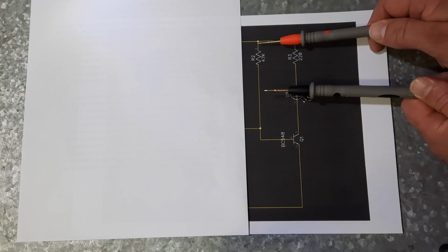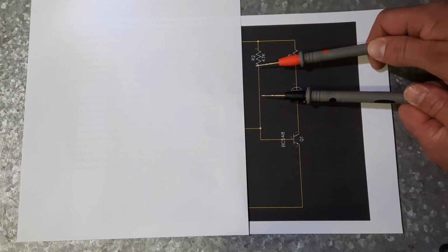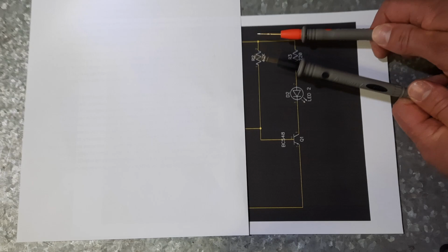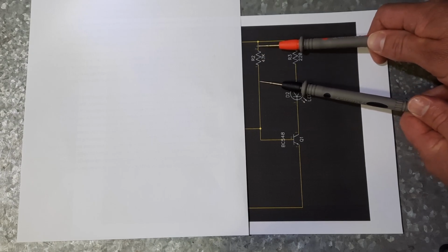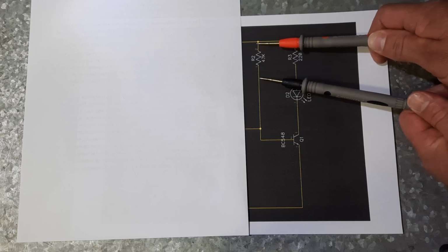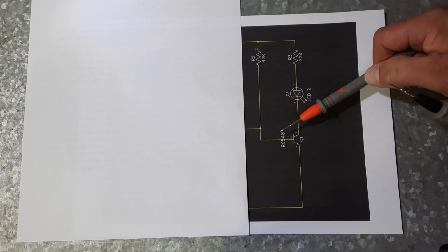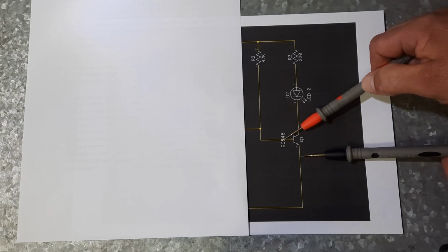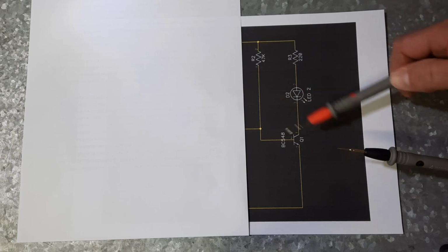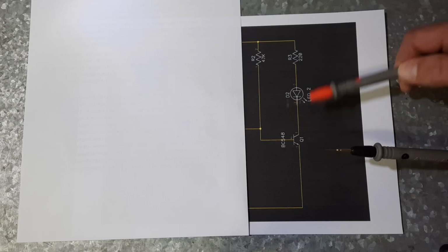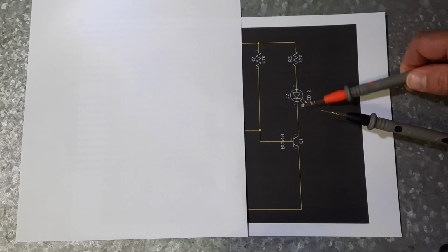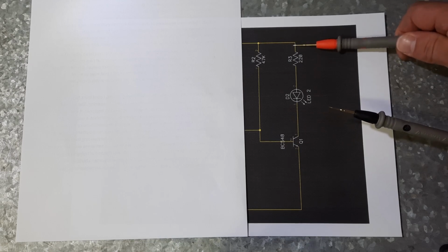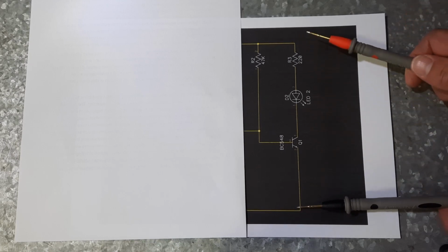So that means that this resistor is dropping the rest. So if we measure from here to here, with it on, with the battery on, we'll get about 8.3 volts across this. And if we measure from here to here, we'll get about 0.7. The two added together have to equal 9. Same as what's happening here. These 2 volt drops here have to equal 9 volts because we have 9 at the start and a negative here.